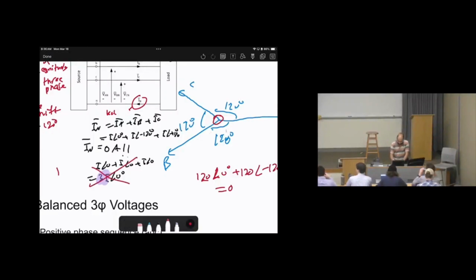Because high neutral current, high I neutral, is undesired. Therefore, we choose to have a phase shift so we can get 0 neutral current. How can we take the benefit of this? This benefit will allow us, since the neutral current is 0, to sometimes remove the neutral. In some applications we can remove it. We will discuss this next lecture, but here I'm just telling you that we are trying our best to make the neutral current as low as possible.